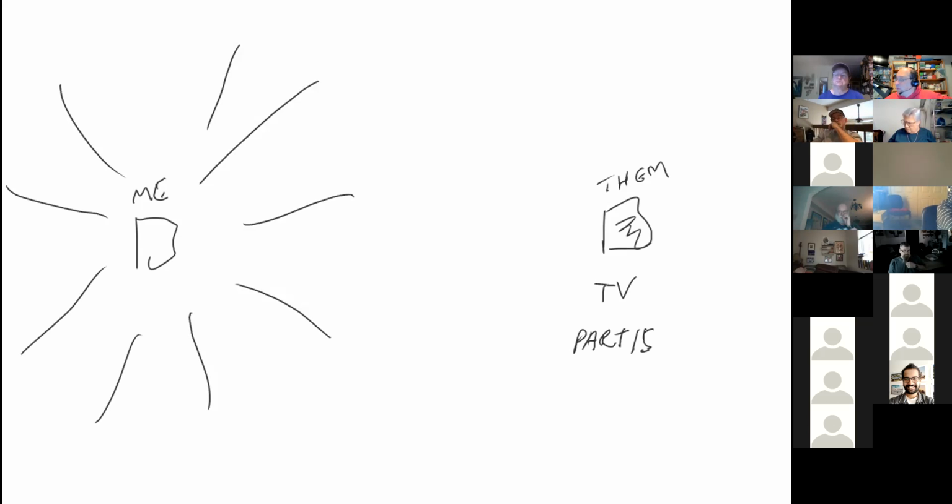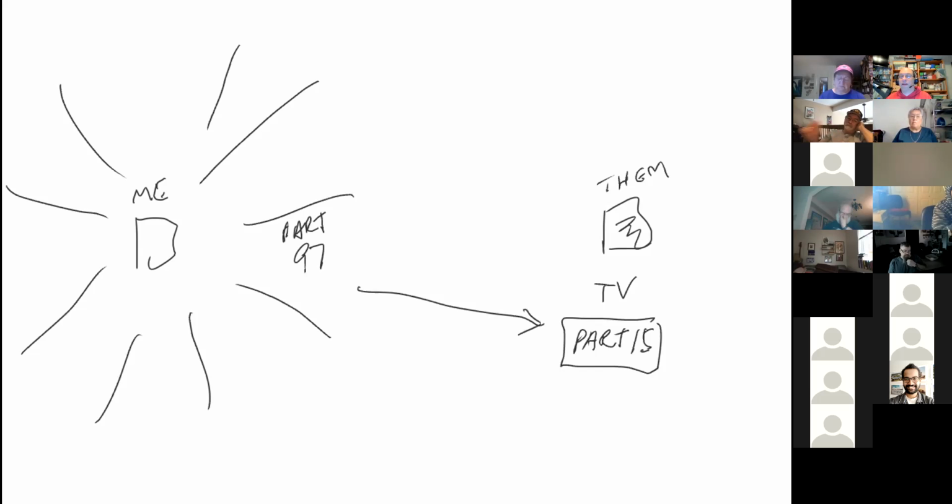Well, ham radio is Part 97. That is the part of the FCC rules that governs amateur radio. Part 15 is an unlicensed device, right? So who's in the right and who's in the wrong if I am interfering with that? They are. Now, the other part of it is that, let's say that this TV is for some reason electrically noisy and it is interfering with my ability to listen on my frequencies. Who's at fault? They are. They are still, that's right, because they're interfering with a licensed service.